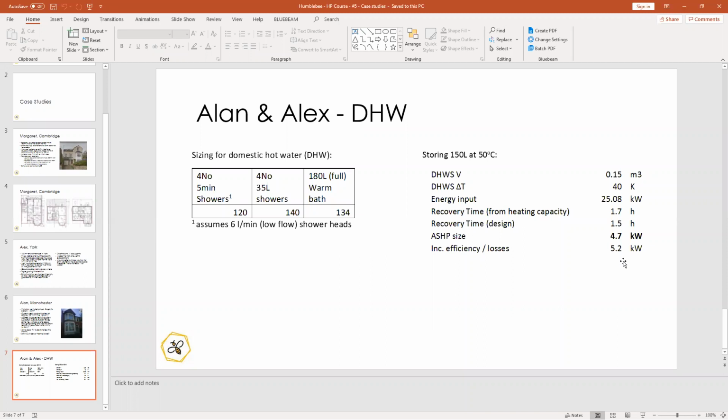There's 4 of us in our house, and we run a 250 tank on an air source, and we've never run out of hot water. You have a 250 tank on a 5 kilowatt air source? Yeah. So there you go. It takes about 90 minutes. To be honest, I've never actually depleted it right down to 10 degrees and then timed it back up to full temp. But it just does its thing.